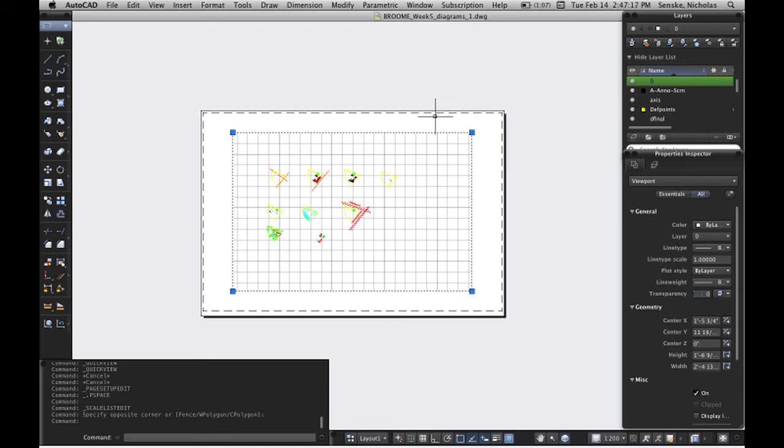If you have a large enough building, you might want to talk about it at 16 scale. If you have a residential house, you might be talking about 1/8 or 1/4 scale. For details, you're talking about 1 inch equals 1 foot, or even a 1/2 inch equals a foot. You begin to understand what drawings want to be. Site scale might be 1 to 1,000, might be 1 to 500, 1 to 200. So this is a good opportunity to get a sense of that. I'm going to give you some ballpark ones for today, so you're not just throwing stuff at it. I think a good scale for the diagrams is probably 1 to 200.